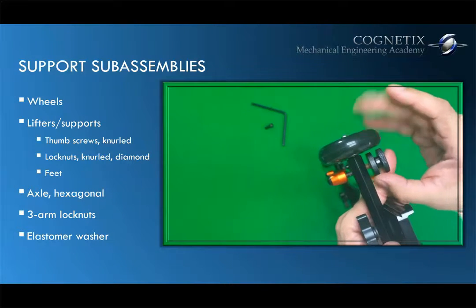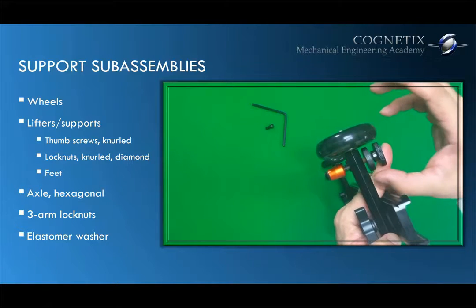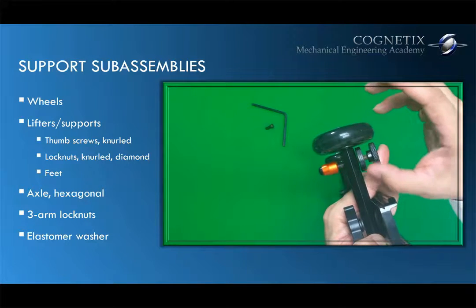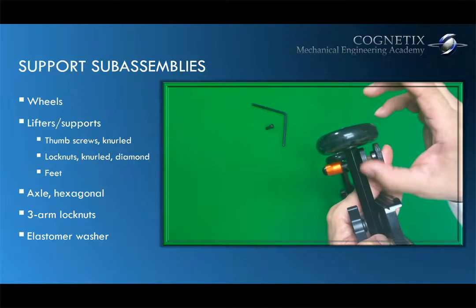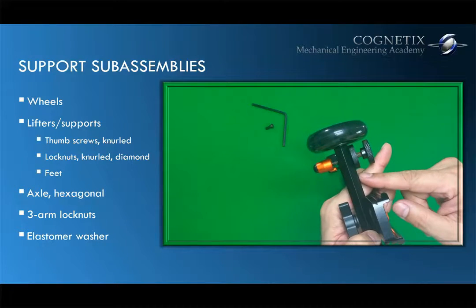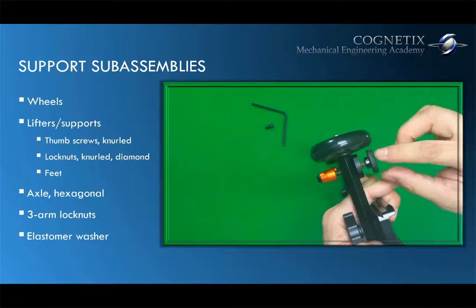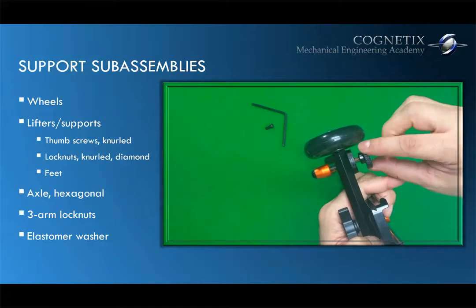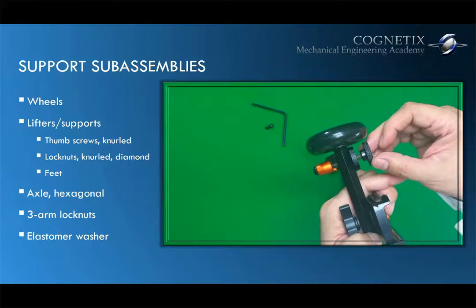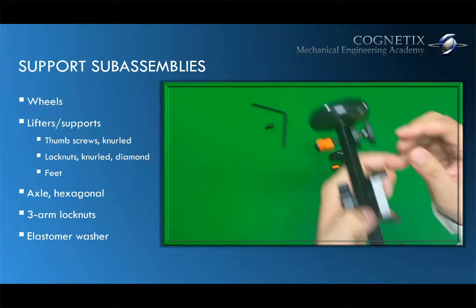I'm going to hold the thumb screw, and I'm going to spin only the lock nut. And you can see it going downward. And if you spin far enough, you're going to make contact with this hexagonal surface here, which serves to lock not only the capability of being able to turn this thumb screw, but it removes the play of the assembly. So now you have a very stable foot that's not going anywhere.